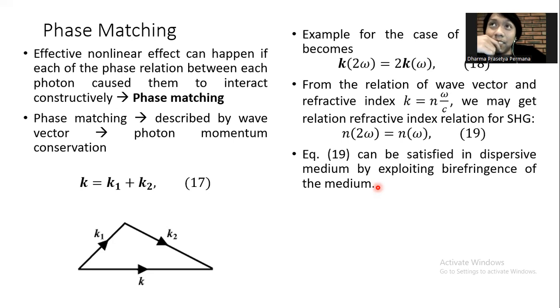In my experience, it's not only dependent on how good the materials are, because a material may have defects in its crystal structure. But when we create a waveguide using it, it also depends on the geometry of the waveguide. So there are so many factors that can affect this phase matching condition.